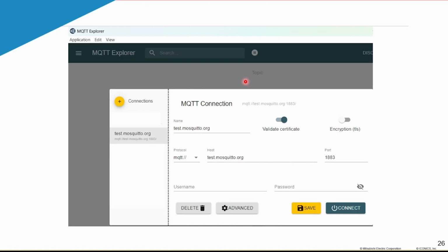If we use the third-party MQTT Explorer, we can set up different connections. It's not just for showing what we publish on Genesis. You can also connect to other brokers, such as the Evercom server, or any of your customers' brokers. Where do we get this MQTT Explorer? I just Google and look for MQTT Explorer, and it will come up. It's freely available to download. It's a good tool for testing.